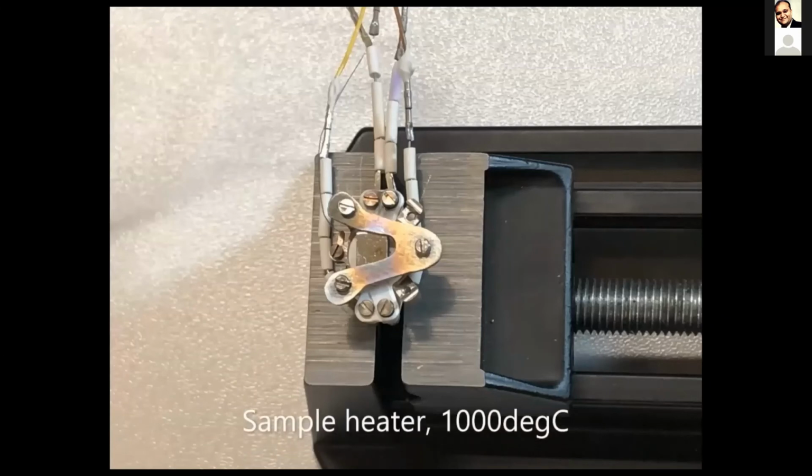This is how the sample heater looks assembled together with the sample and the Horseshoe clamp on top. The 3 screws are threaded in to hold the sample tight against the heater below. And the left-hand side is what's going to be mounted towards the top of the pico indenter. So you can see that it's open, allowing for a viewing window from looking with the electron beam from above. Typically, testing is done at a tilt of 10 to 20 degrees to allow good visibility of the sample.